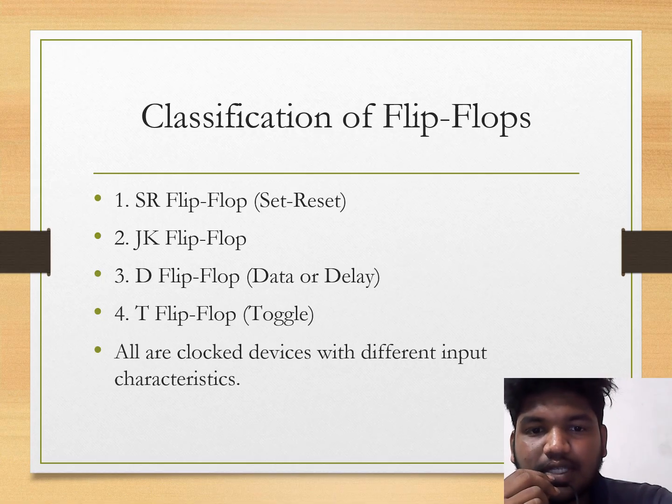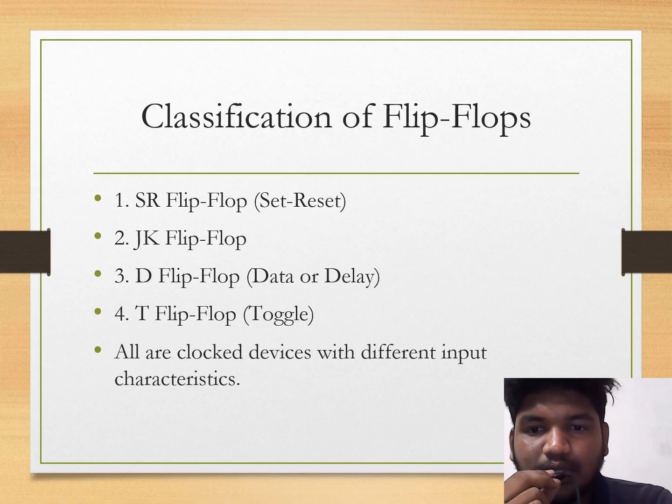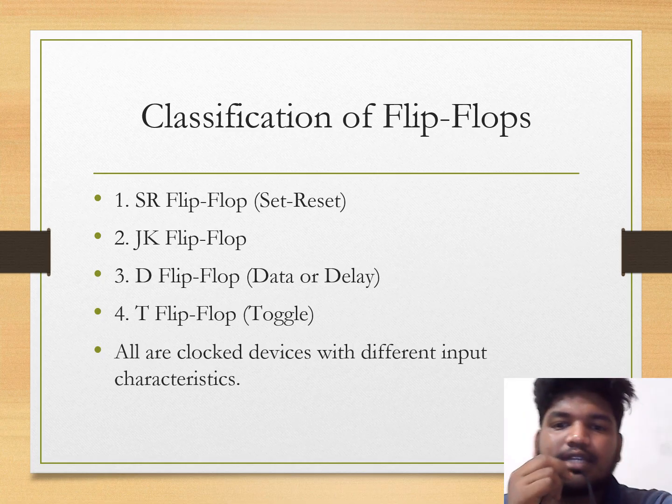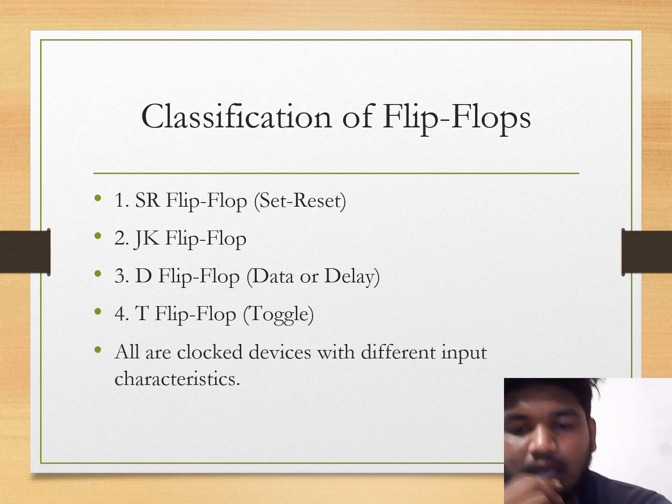All the devices have different clocks and input characteristics. And I'm saying that flip-flops are used to store the data. We have four types of flip-flops: set-reset flip-flop, JK flip-flop, data or delay flip-flop, and toggle flip-flop.